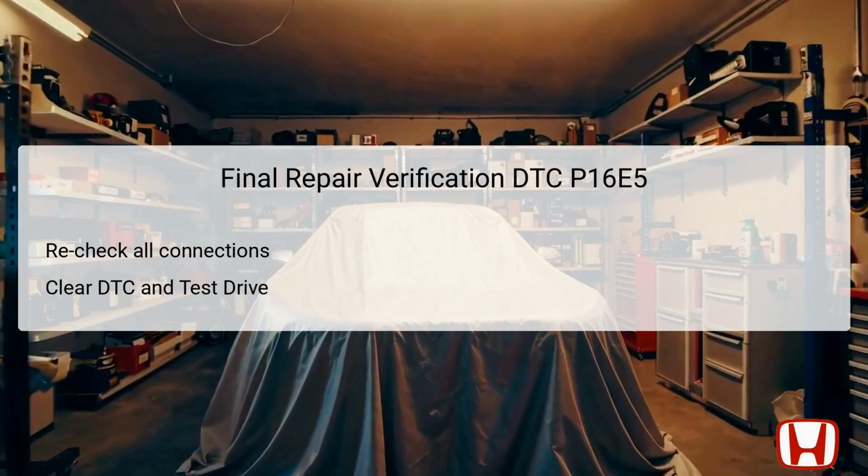After completing all troubleshooting steps and necessary repairs, final verification is essential. This involves rechecking all electrical connections and ensuring that everything is securely fastened and correctly reconnected. Once verified, clear the DTC from the memory of the Powertrain Control Module using Honda Diagnostic System (HDS) or appropriate diagnostic tools.